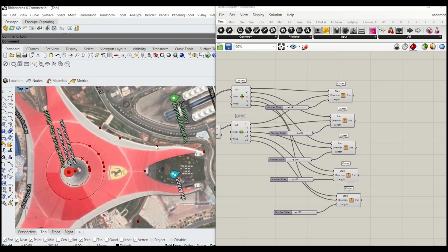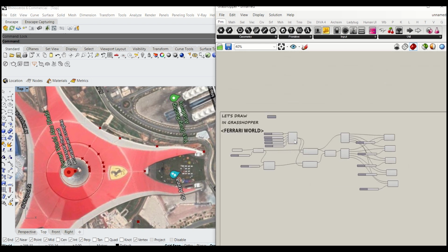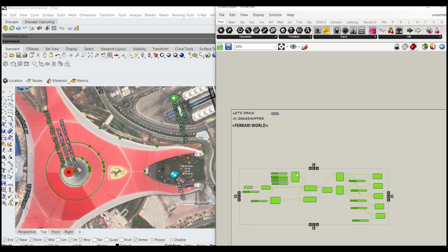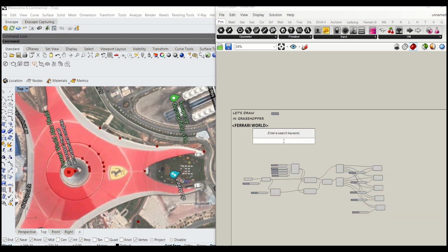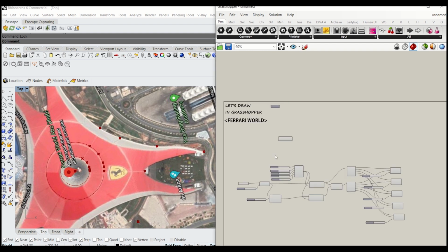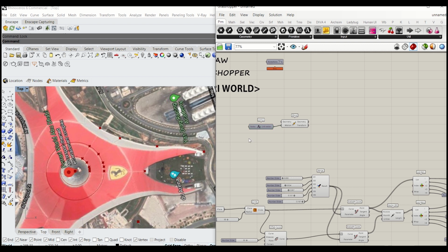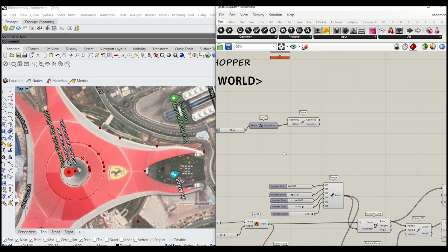So we'll need to bring these up to Z coordinate as well, because we're not just going to build this in a flat surface. So let's give that an action. Let me just bring this all slowly down so that I will have some space at the top. So what we need is, we're going to repeatedly use this command, moving in Z direction. Okay. So the building, I don't imagine that goes beyond 60 meters, probably do, but you have flexibility going all the way up to 100.